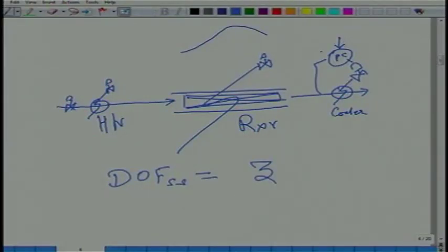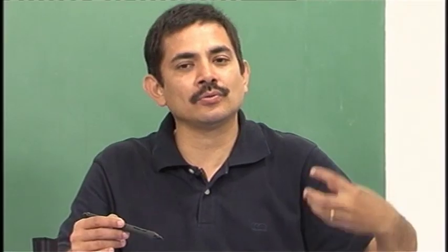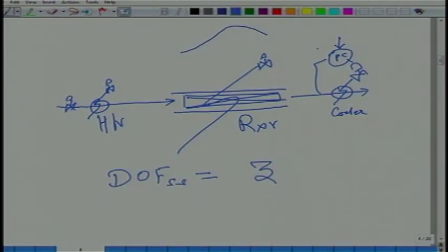I am not discounting it, because if the pressure set point is increased, what happens to the reaction rate inside the plug flow reactor? It will increase. Usually it will increase. If I decrease this pressure set point, the reaction rates will go down, because reaction is proportional to partial pressures. Higher the pressure, right? So in that sense, the degree, even though this is an inventory controller, this inventory must